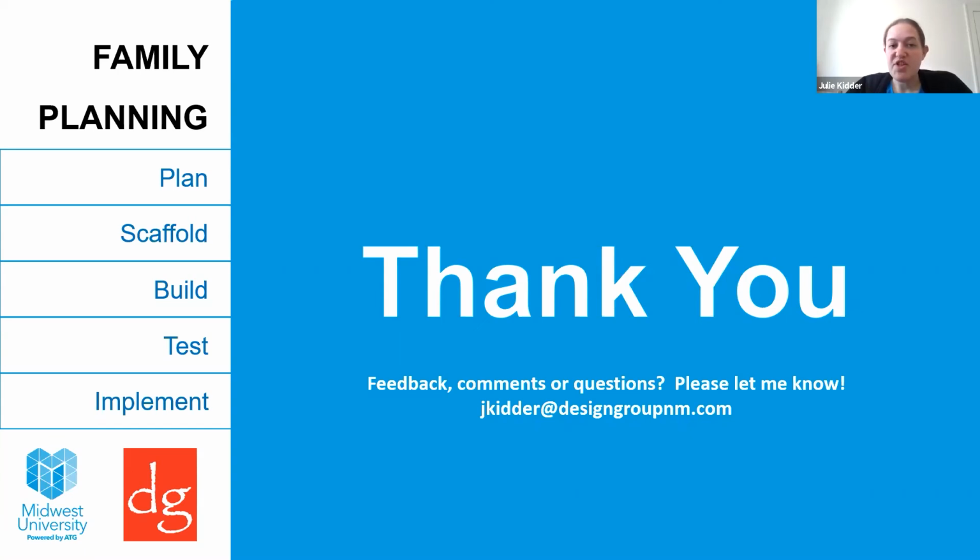Next question is, you mentioned not seeing the clearances for the doors in all the views, but did not mention how I accomplished that. So what I ended up doing was, the original doors didn't have the clearances on a subcategory in the door family. So now the clearances are on two subcategories, one for plan view and one for the 3D view, so that those can be controlled independently.